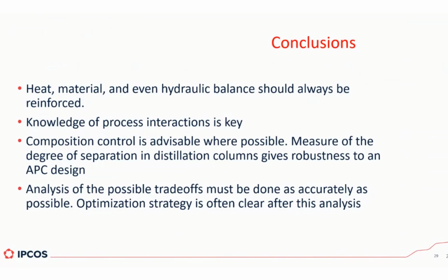So we use our engineering knowledge to see which are the variables that will help us estimate that property in the most accurate way possible. Just as I showed you, the soft sensor that we created with the reflux ratio and the boil up ratio, that in itself is somehow a bit of a first principles model.